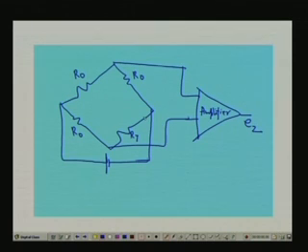Now this cold junction compensation circuit, as in the case of AD590, should also be placed close to the reference junction, so that any fluctuations in temperature of the environment will be nullified. In that case it will sense the temperature of the cold junction. Ideally they should be within the isothermal block, and the total circuit is shown in the next slide.